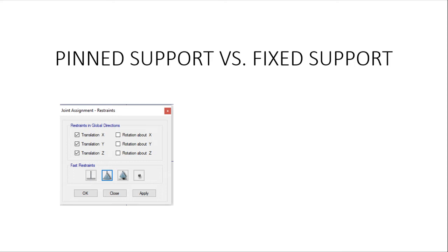restraint about the translation in X, Y, and Z axis. So we are not allowing any displacement in X, Y, and Z directions at that node. We all know in a 3D frame, di ba? Each node has 6 degrees of freedom, tama? Pero kapag at that node is pin supported, ngayon nagiging 3 degrees of freedom na lang siya. So ang tanging meron lang sa kanya is meron siyang rotation sa X, sa Y, and sa Z, pero wala siyang displacement in X, Y, and Z directions.